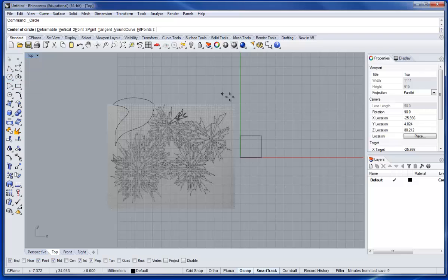We can also generate circles from this, and you can do that to generate arcs. Again, the rectangle tool, I use that down here. A lot of these, whenever you hit one of these command lines, it asks you for these details. So we have the center of the circle here, that's what it's asking us for. And then we can start to edit some of these things, the type of circle, 2-point, if it's going to be vertical, tangent, around the curve, or fit to points. These are features or settings within the tool itself. Like if we go to start drawing a curve, we can set the degree of this. If I set the degree to 1, then it becomes a polyline. Okay.